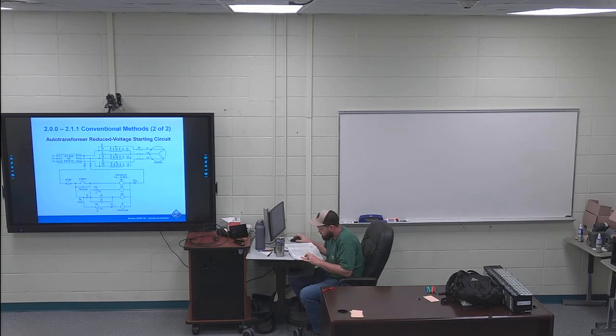Its normally closed auxiliary contacts also open, causing contactor 2S to de-energize. So R right here will open up, 2S will de-energize. Note that during the transition from starting to full line voltage, the motor was not disconnected from the circuit, indicating a closed circuit transition method of operation.